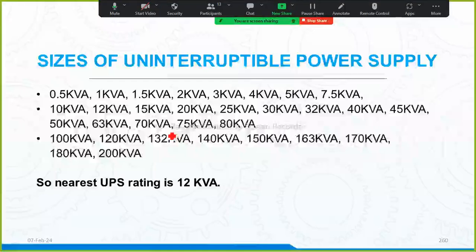Because in your loads, there are inductive loads, where the drawback is that they take high power at the time of starting. So when doing the generator and transformer calculation, we were just checking whether my proposed transformer or generator will be able to withstand that much load or not. When it comes to your UPS, we don't have inductive loads. We have only lights and fans on normal sockets. So in the UPS calculation, we don't do any checking of the UPS. That is final, which is 12 kVA.